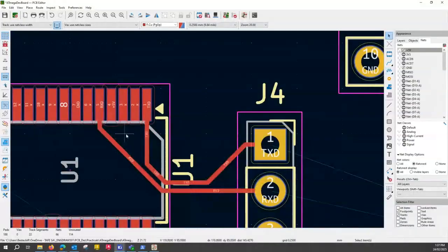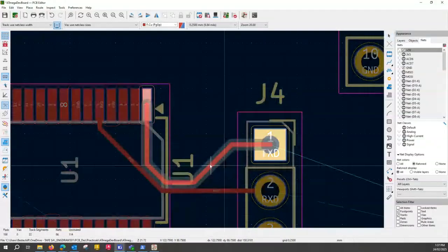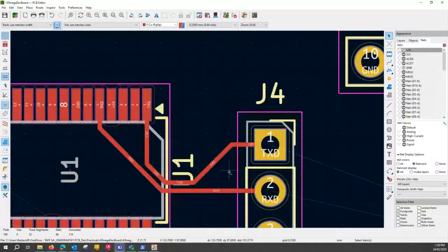Now, what we have here is we've got 5 volts coming here. We can come from the outside, which means there's no issue with that space being closed. We also have those unconnected pins, that's fine. We just need to make sure that we connect this ground plane to a common ground, and the same on this end. So we could either create this one a little bit larger space, just to make sure that we can put ground stitching via through those 2 areas, or we could space them up so it just floods that whole area, the ground will flood this area, but I'll leave it as this. So that's okay for communication side.